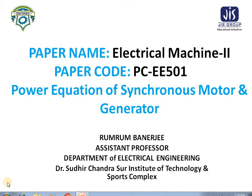Basically, a synchronous motor is a machine that converts AC electrical power to mechanical power at a constant speed, which is called synchronous speed. Synchronous motor is also a doubly excited machine like the synchronous generator, and its rotor is excited by DC current and the stator winding is connected to the AC supply. The air gap flux is the resultant of the flux of both rotor and stator.